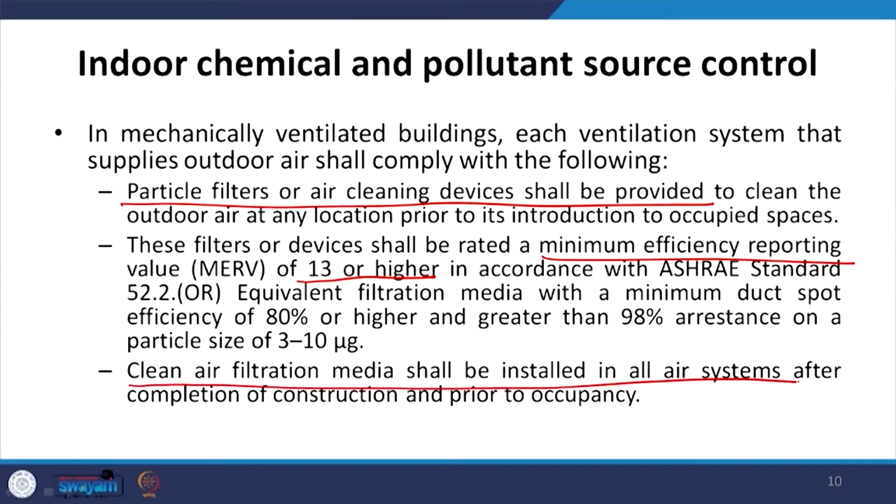Also, the clean air filtration media shall be installed in all air systems. So, not just where the hazardous chemicals are being produced inside the building, but also when the outdoor air is being brought inside, the air should be cleaned properly. The dirt, the pollutants from outside should not be allowed to enter inside. The intent is to ensure that the building's occupants, the human beings who are inside the building, are not exposed to pollutants and they remain healthy and sound.